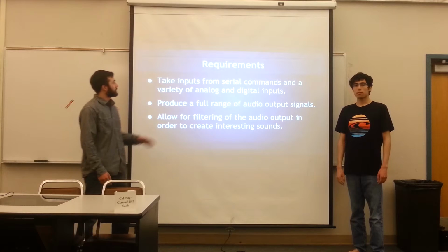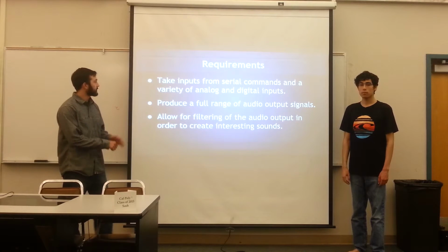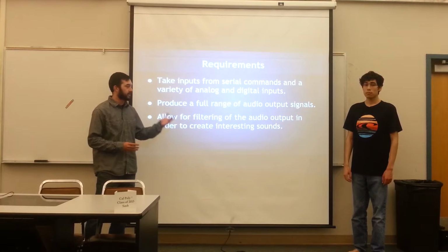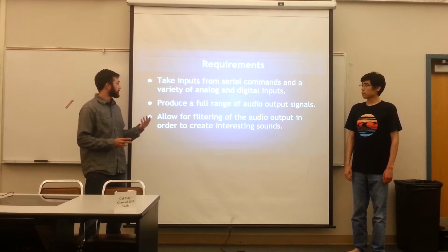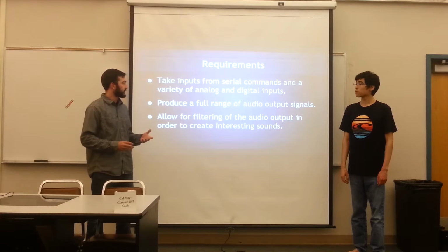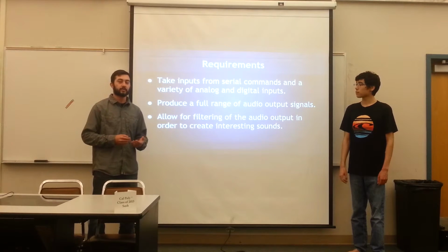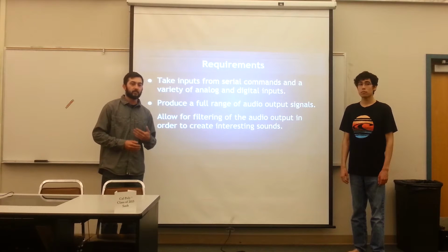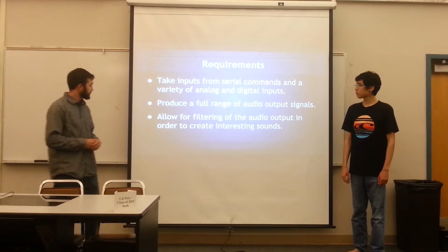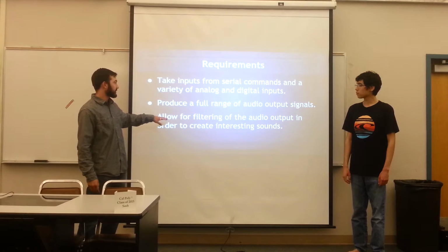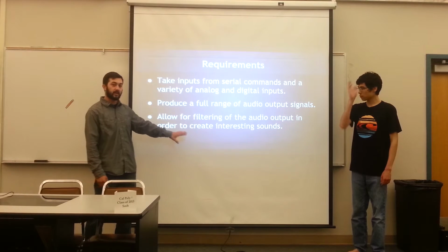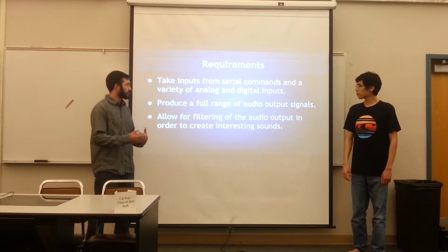Real quick, the basic requirements of our system is you want to be able to take inputs from serial commands and a variety of analog and digital inputs, and be able to produce a full range of audio output signals. This was just so that we can make it easy for a beginner user to hook this up and then immediately begin producing music. And also we would like to allow for filtering of the audio output in order to create interesting sounds. This would be more of our Rev 2 with that ADSR filter, just to increase the complexity.